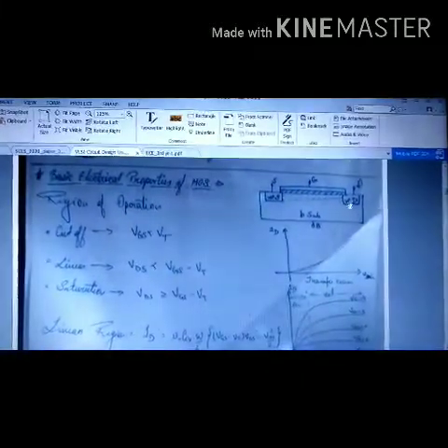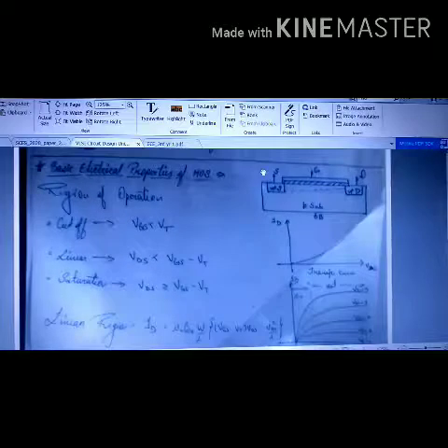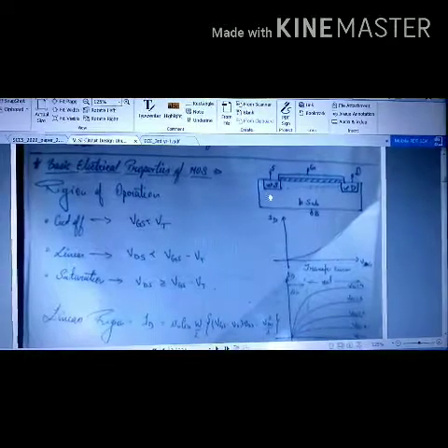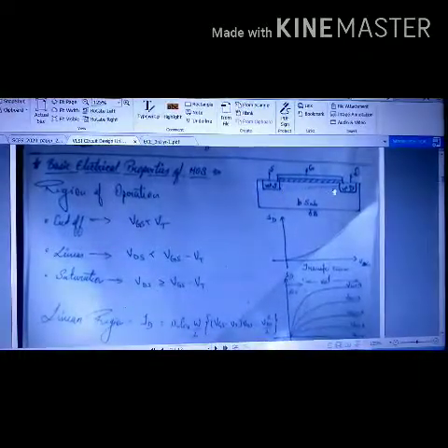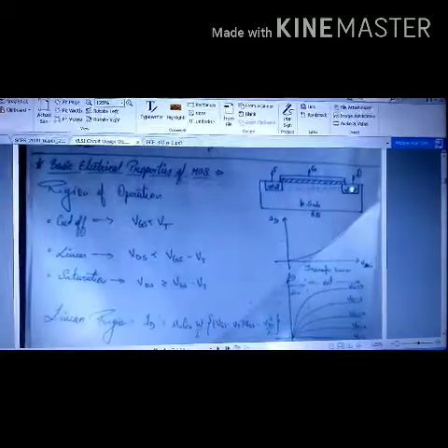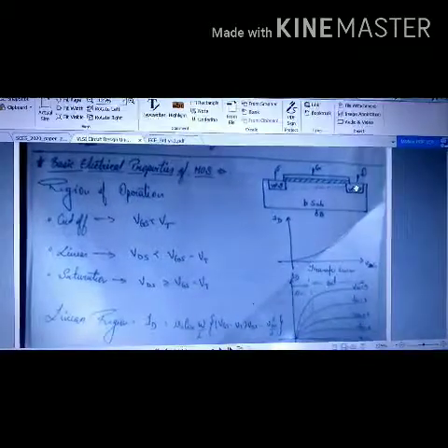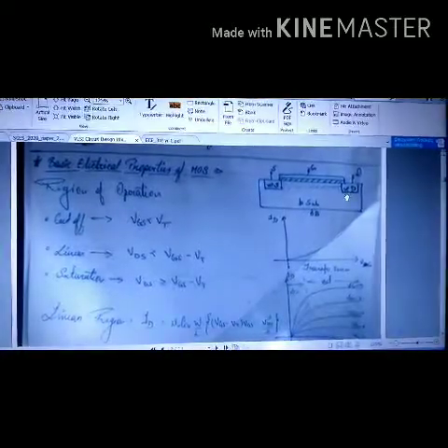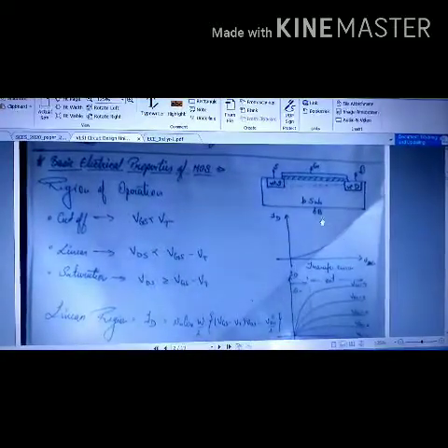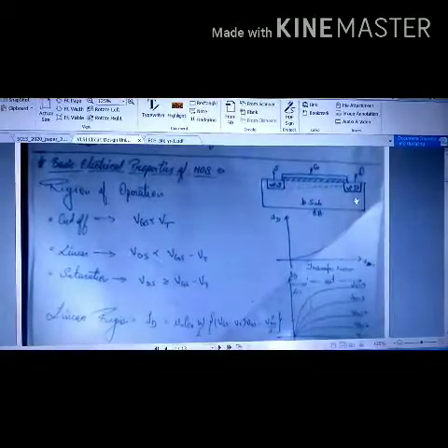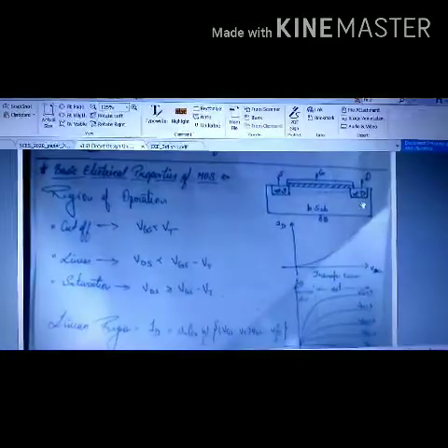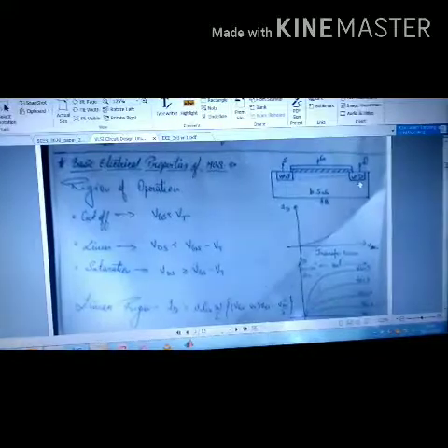Now this happens because the source electrode is grounded, so only a small depletion layer is formed below it. However, since the drain potential is continuously being increased positively, and the positive drain is connected to N type material, and the body is also grounded, so the P type is at zero potential, this results in the drain and body forming a reverse bias diode.